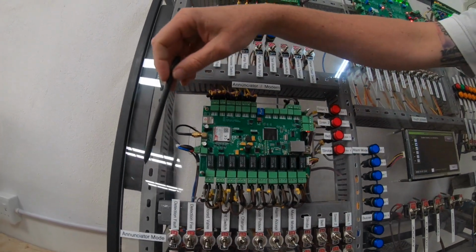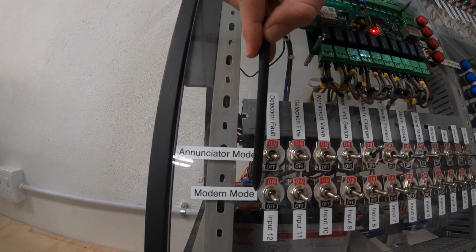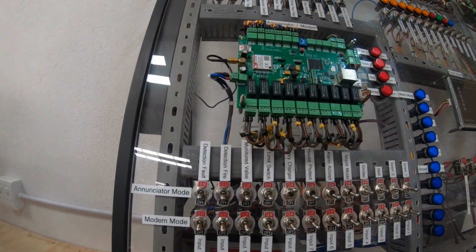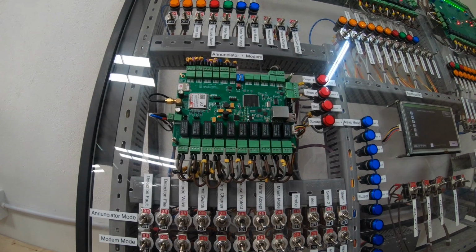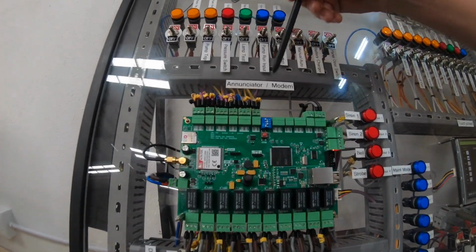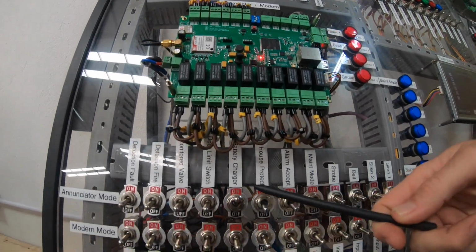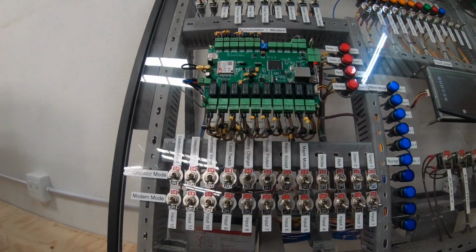With regards to the annunciator, we have two separate modes. We've got the annunciator mode and modem mode. We'll go through the annunciator. Annunciator will be linked for the sprinkler systems, which is linked to your jockey pump, your diesel, your electric controllers. We have 12 digital inputs. These inputs we've linked to limit switches or toggle switches where we can activate predefined conditions.